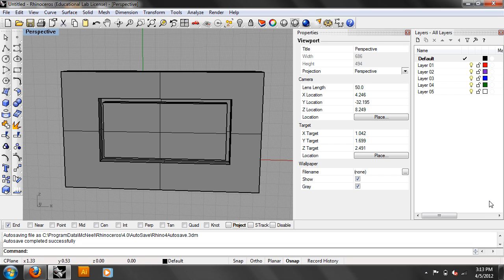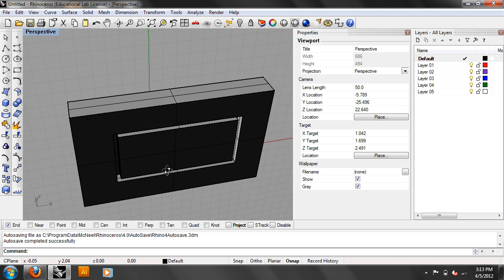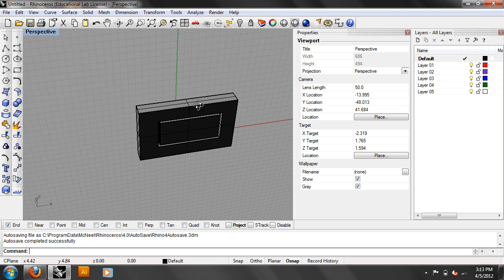You can group things, like different lines from different layers. Yeah, groups are just temporary, arbitrary assignments. The way I did it was essentially to group things on the layers, but groups can work across layers. You just have to be careful with that. Rhino kind of violates some rules, but I think it makes sense when you're using it.